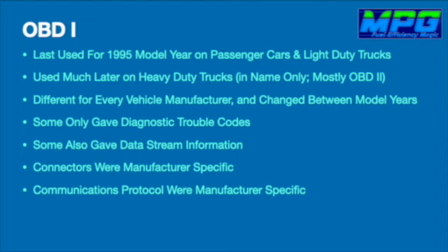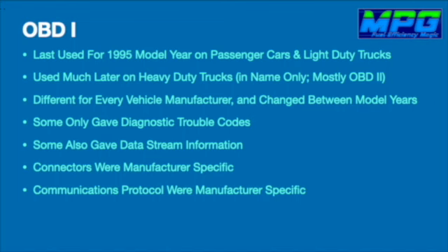Some of the car companies started going with trouble codes. So at least you got like a code 13 coolant temp circuit or something that pointed the technician in the right direction. And then we got data stream information where if it had a coolant temp sensor code, the technician could look and see what does the computer see for engine coolant temperature.